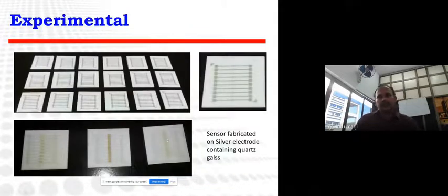So a number of patterns we printed and tested. In one case, what we observed is that, as I told you previously, the glass also plays an important role. We want to measure the second part of our sensor for high temperature application, above 500 degrees Celsius, and our synthesized glass has a Tg of 670 degrees Celsius. So we thought, can we use quartz, because quartz has a high softening temperature, in the silver paste, and so we fabricated patterns for high temperature sensor application using quartz glass.